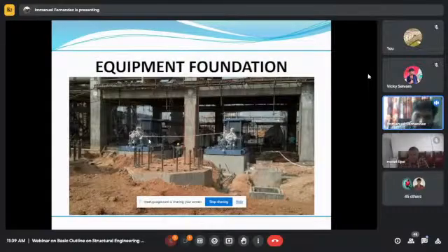And these are the equipment foundations. We have the pedestal, the structural component, and the anchor bolts here, above which the process columns and vessels will be erected. Behind this you can see a pump, and this is a block foundation. In this block foundation we do the rotating and dynamic analysis, and then we ensure the block is adequate to take the load of the pump. The main objective is that there shouldn't be any resonance. The frequency of the pump shouldn't match the frequency of the foundation.